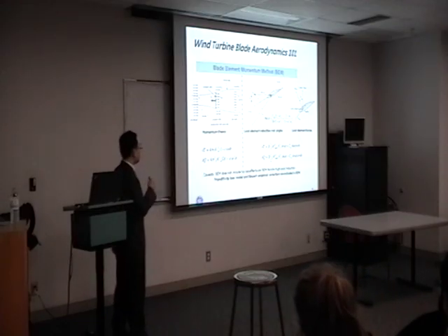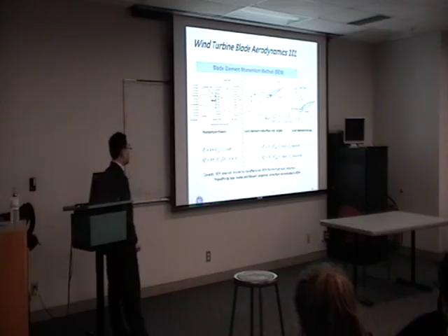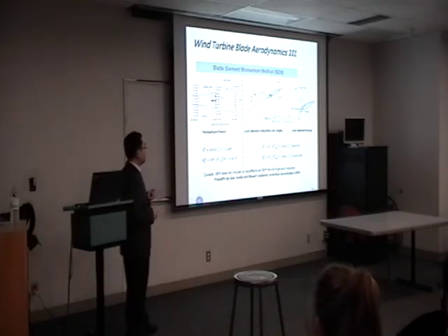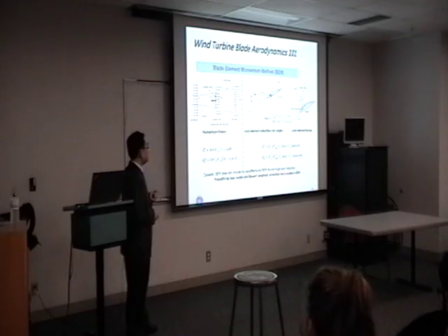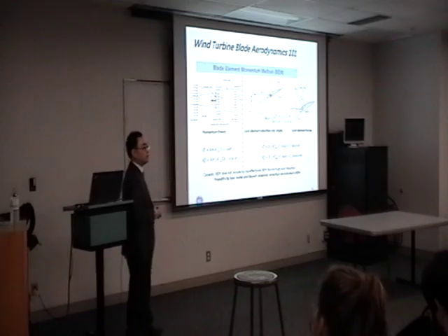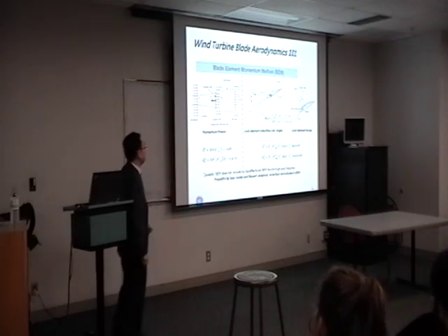However, there are caveats we need to be very careful about. We didn't consider the blade tip loss effects, and also it does not work very well for high axial induction, simply because the momentum theory fails for very high axial induction cases. So we implement the Prandtl tip loss model and Glauert empirical correction to complete this method. By the way, this method is called the BEM, blade element momentum method.